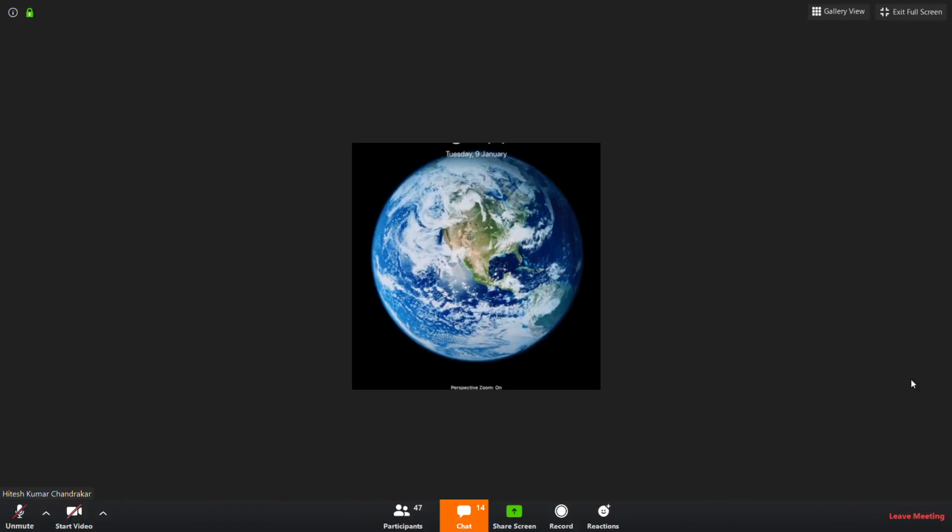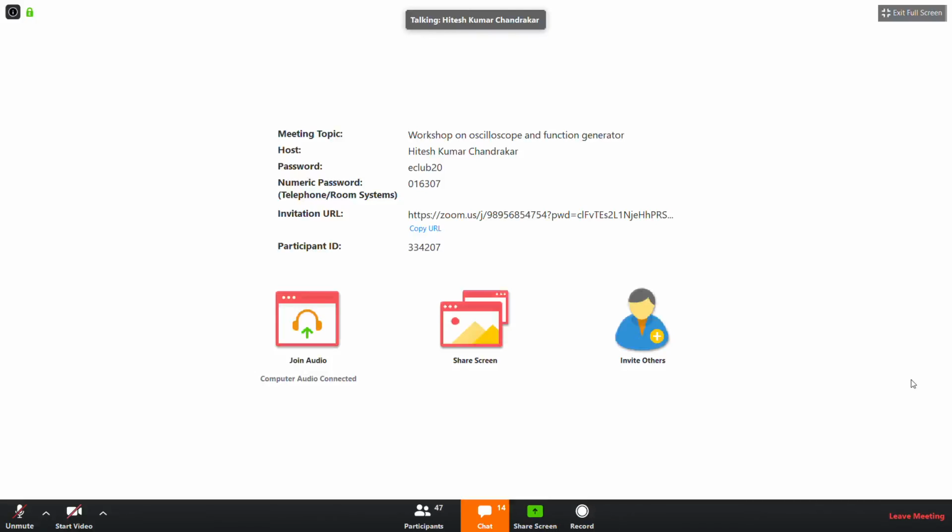As I told you in the drawing, channel 1 is sine omega t and channel 2 is sine omega t minus 90 degrees, so it is basically cos omega t. When your x-axis is sine omega t and your y-axis is cos omega t, you get a circle. That's why we are getting a circle.